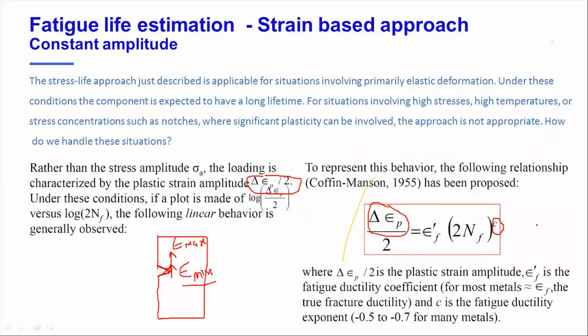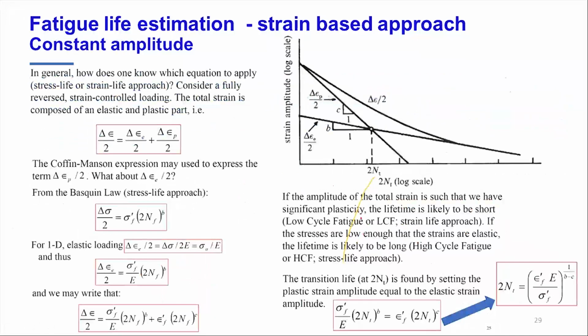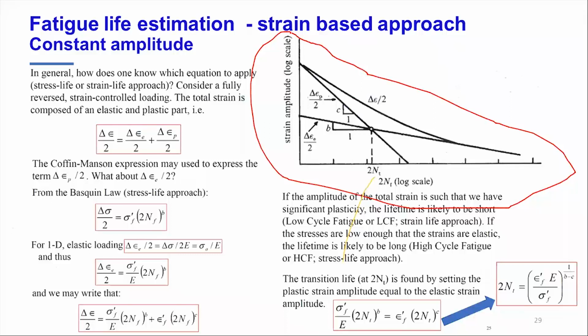So what you have to do from your simulation point of view is take the delta of strain, and use these Coffin-Manson curves, which will be available in your fatigue handbooks or maybe other material databases. So you take your plastic epsilon range, and see, for whatever range you have, how many cycles you can sustain.